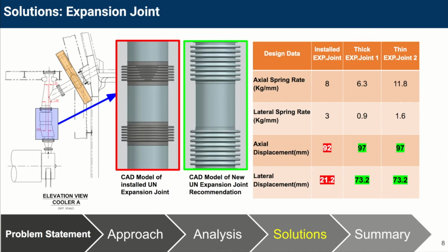After communicating with expansion joint manufacturers, two new expansion joints were designed, both of which include thicker, larger, and more bellow convolutions than the existing design. The thinner bellows will allow for the required movement without as large of a spring force as the thicker bellows. This will impact the spring hanger force necessary. Ideally, we would like a design that has the least impact on the overall system. Therefore, having an expansion joint that does not require a brand new spring hanger will be beneficial.